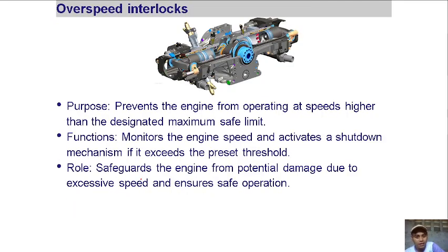Okay, another protection device for our engine is the overspeed interlock. If the engine moves faster than its rated speed, it goes overspeed, so there will be a big chance that the engine will be damaged. It prevents the engine from operating at speeds higher than the designated maximum safe limit.